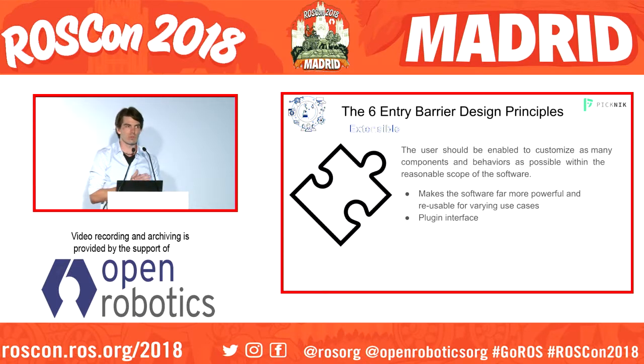In MoveIt, we're really into pluginlib. That is a little faster in terms of communication. Hopefully ROS 2 fixes that. But with pluginlib we have 8 different types, so collision checkers, planners, IK solvers, etc. And if you don't like one piece of that, you can pull it out and extend it to your own research or to your own particular need.